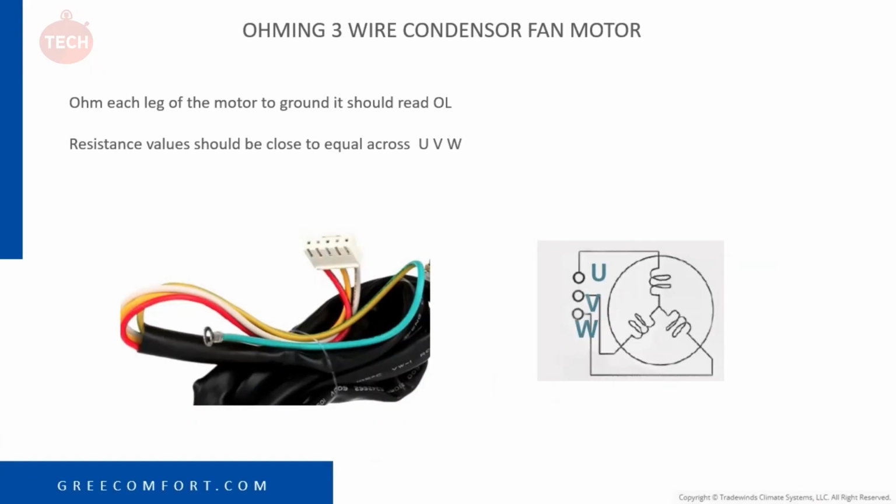So don't just think it's going to be the same every time. As long as we're close to equal between the 3 windings, that's what we're looking for. And of course, each leg to ground should be OL: U to ground, V to ground, and W to ground. If we get a reading there, we're shorted, and we want to replace that condenser fan motor.